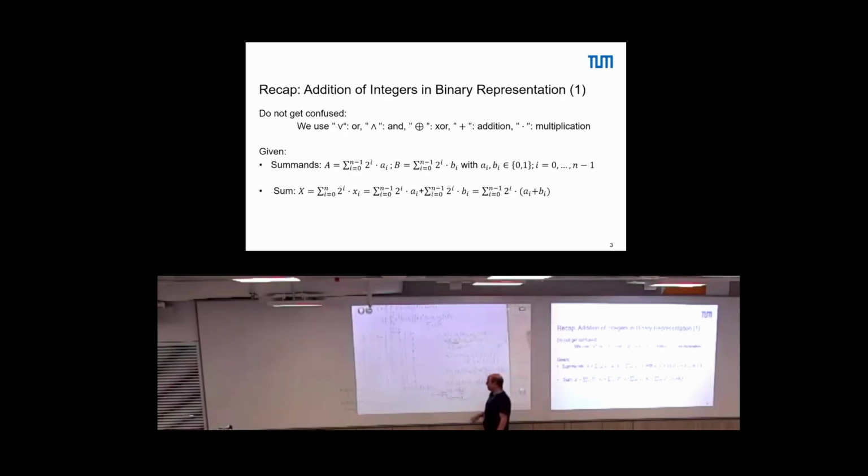So now we also want to generate the SI. We have already AI XOR BI that we already have computed. So the only thing we need is to compute the result of this here XOR the CI minus 1. So we put here another XOR. We connect this here to CI minus 1, and this here is SI. So now, with the three inputs, AI, BI, and CI minus 1, we can generate SI and CI. And this is commonly known as a full adder.